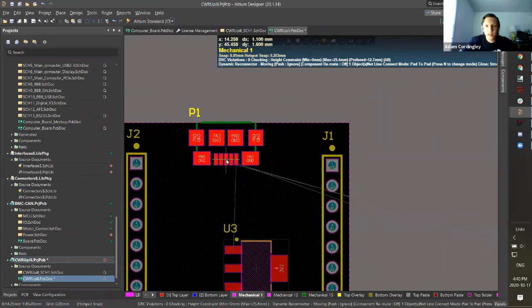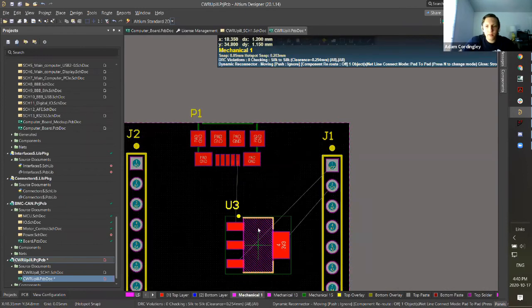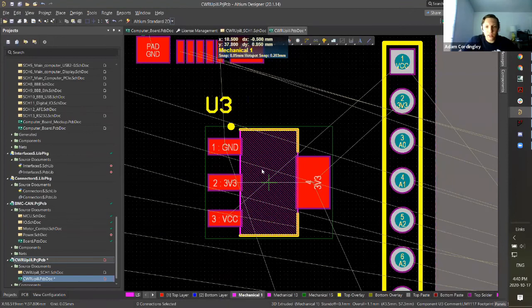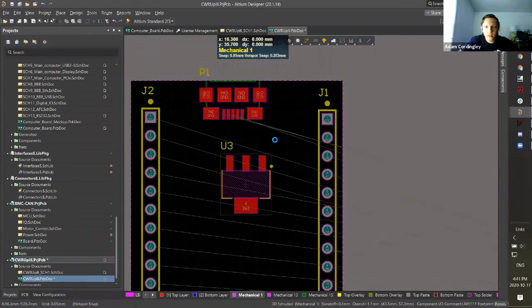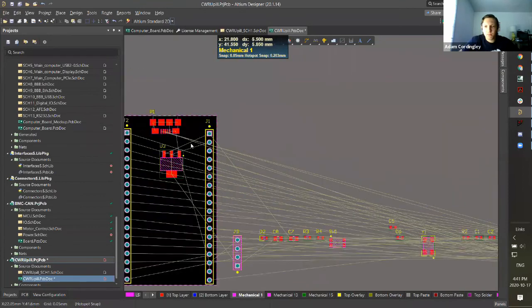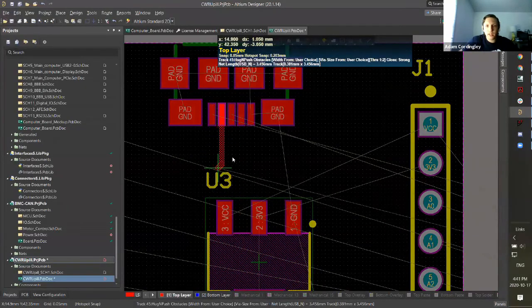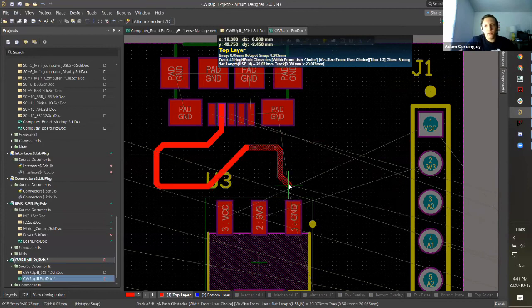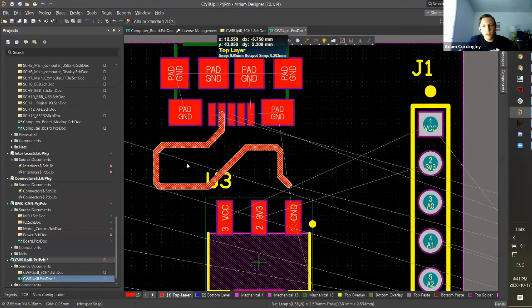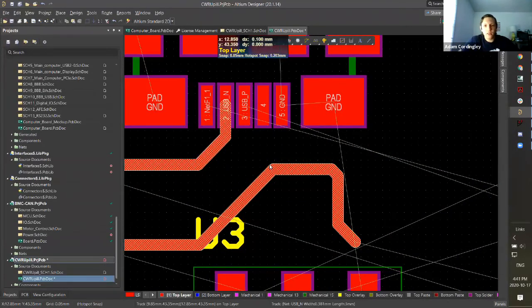They're a lot like they sound, but I'm going to take the example of this linear regulator. So I can, of course, connect things with tracks. Again, in this toolbar, you can hit this tool, Interactively Route Connections. And that'll allow you to take a track and route it to stuff. You can see it kind of helps you out a little bit. You can do whatever you want, you know, write your name with it, whatever. And this is a part of a differential pair, so it's complaining.